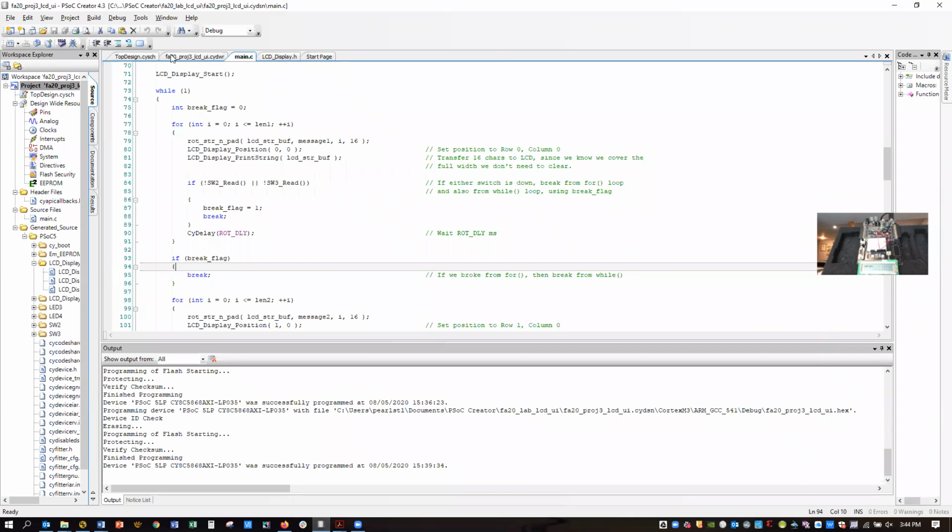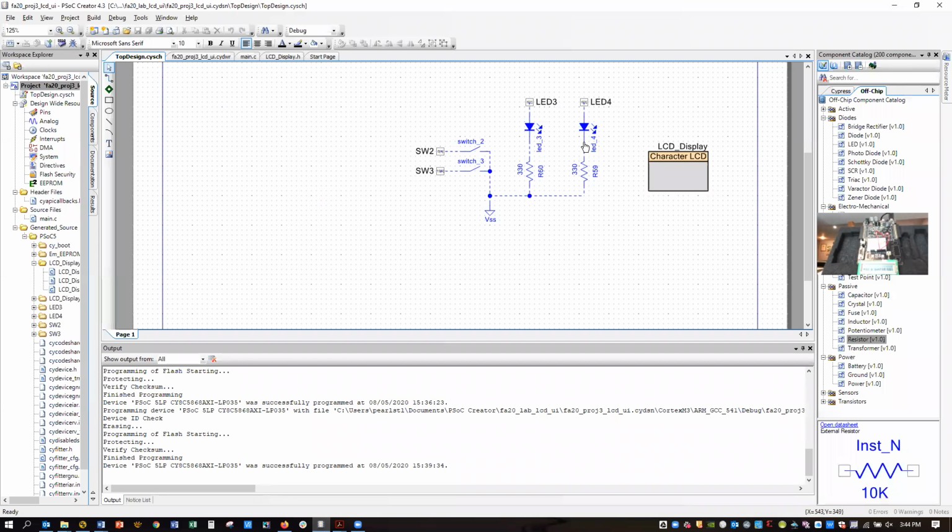If we look at my schematic, I'm just showing the LEDs and the resistors that are on board. These resistors limit the current. The LEDs themselves drop about 2.1 volts. And the assumption here is that the supply voltage, the pin voltage here, is 5 volts, although the boards can be set for either 5 volt or 3.3 volt supplies. Either way, you'll get enough current to light the LED, but you might want to assume that the high voltage, when a logical 1 appears at the output of a pin of the chip, will be driving roughly 5 volts.